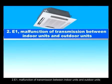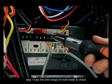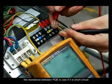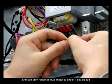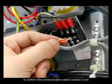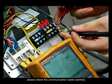2. E1, malfunction of transmission between indoor units and outdoor units. Repair instructions when E1 appears. Step 1. Use the OHM range of the multimeter to check the resistance between PQE to see if it is short circuit, or short connect PQE on the other side and use the OHM range of the multimeter to check if it is closed, to confirm if the communication cable is broken or not. If short circuit or open circuit happened, please check the communication cable carefully.